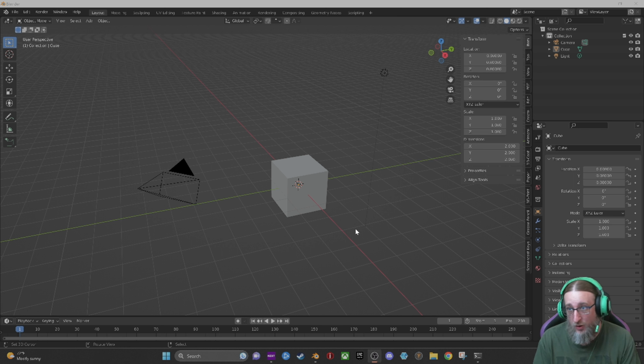The reason you would do images as planes is because reference and background images are not actually in the scene. They're in the background. They're not part of the actual thing. You want something that's actually tangible that you can work with. So click on images as planes, and then we're going to go and find the picture that we want to be lithophane. Now, I'm just using this real quick image here for reference. I mean, it's a super quick and easy one.